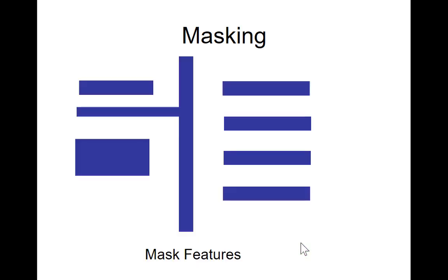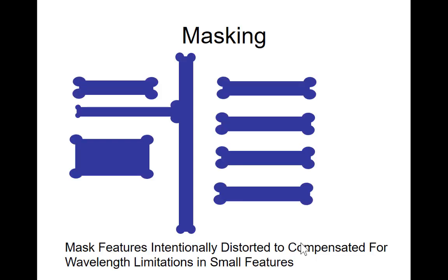And then on the slides, here is how you did it, and especially when it goes to the wafer, the corners may be gone, etc. So this is the mask. You draw this mask, but when you actually go to the wafer, the corners will become roundish. One simple way to deal with that is to compensate a little bit near the corners, and you can do that. And for smaller feature size processes, you need to do even more.